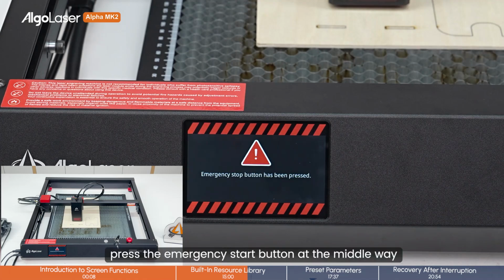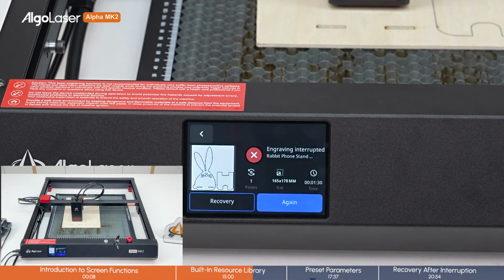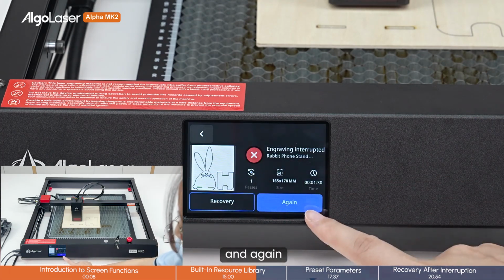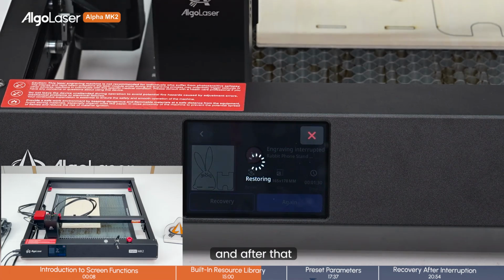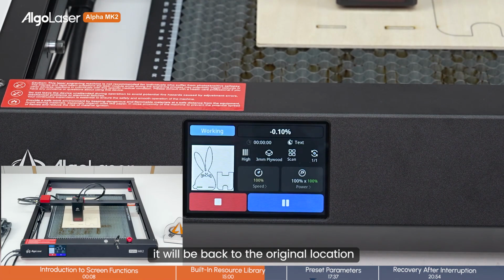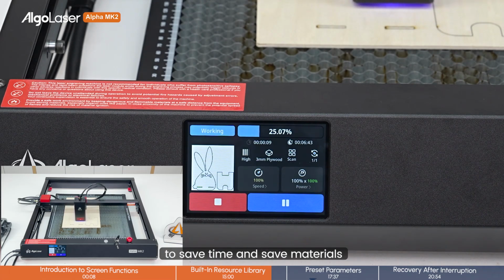So we press the emergency stop button midway, then we click confirm. In the touch screen, there are two options, recovery and again. We just click recovery. Then we wait for the laser head to come in, and after that, it will go back to the original location to continue the laser work. In this situation, it helps you save time and save materials.